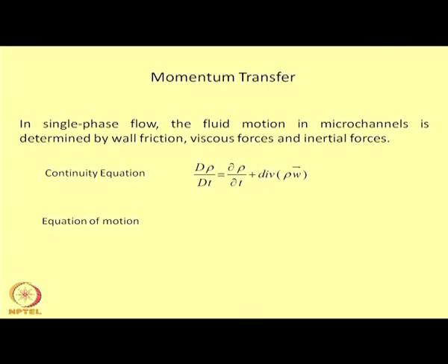are obviously the continuity equation and the equation of motion and so on. So, for the continuity equation, we know that the substantial derivative, that is capital D Dt, of density is going to be a function of the del t of rho and the divergence of the mass flow vector. Similarly, if it is a steady state, then we will simply know that the dot product of velocity times area would be the same, which would give rise to rho 1 V1 A1 being equal to rho 2 V2 A2 and so on.